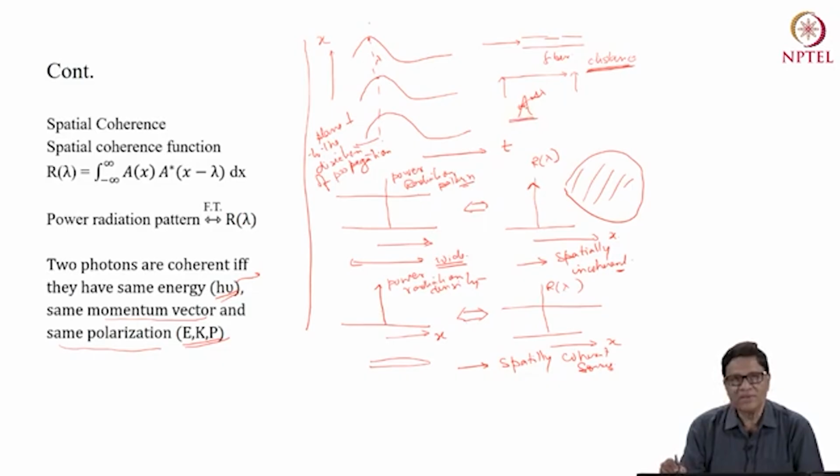But the advantage of a narrow spectral width delta lambda is that the wavelengths inside this delta lambda travel in the fiber without significant dispersion. If this is wide, each wavelength will travel at a different velocity and arrive at different times, so you will see spreading of pulses.